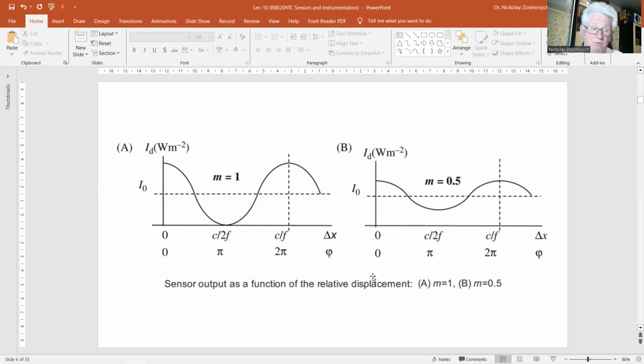In an interferometer, the two waves travel along separate paths, one with a fixed length, the reference, and the other having a length that is set by the movable object, whose displacement has to be measured. Okay? So the two waves fall on the same detector where they are effectively added up.